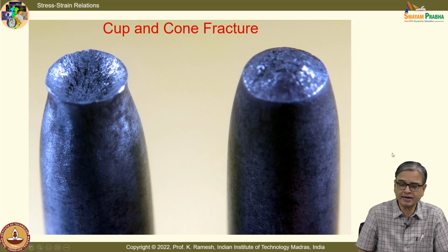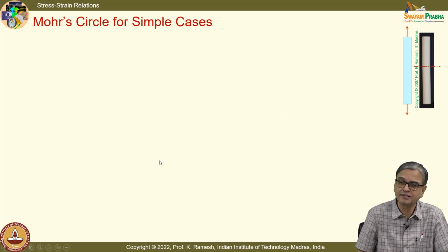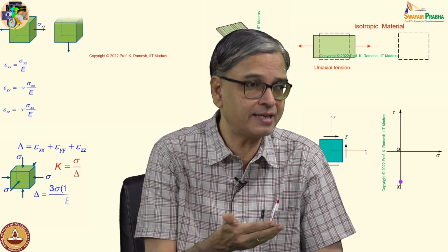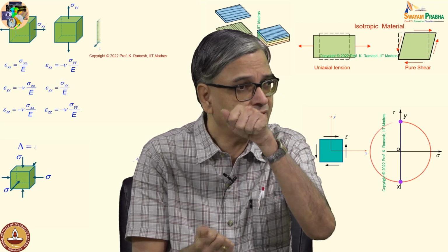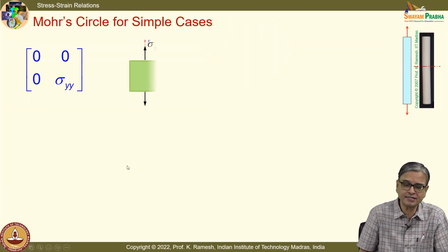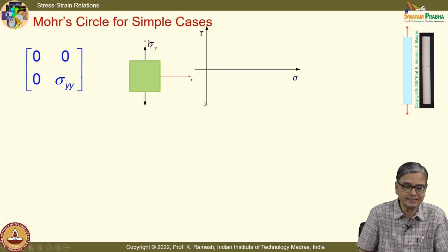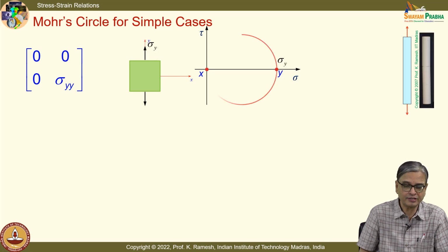And we have also looked at it from the Mohr circle for a uniaxial loading. We have discussed why a chalk fails like this. We have also seen epoxy, which behaves in a brittle manner. In an actual video I showed that when you pull it, it was getting separated horizontally. Fine. So that reinforces the reason that brittle materials fail by maximum normal stress. That can be a good model for your failure theory.